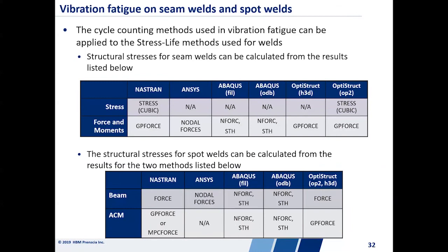The next thing that's worth mentioning is that we can do vibration fatigue on seam welds as well as spot welds. So everything we've seen so far has been fatigue analysis in the frequency domain on parent metal. The cycle counting methods that we've seen can be used in vibration fatigue, and they can be applied to the stress life methods that we use for welds. If we're doing seam welds,